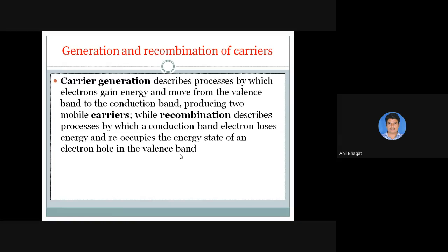The recombination always takes place in a device. Suppose the electron present in an n-type material crosses the junction and recombines with the holes in a p-type material. The recombination takes place in the p-type material, and similarly the holes recombine with electrons in the n-type material, and this recombination releases some energy, in the form of light or something else, and that is used by the LED, right?